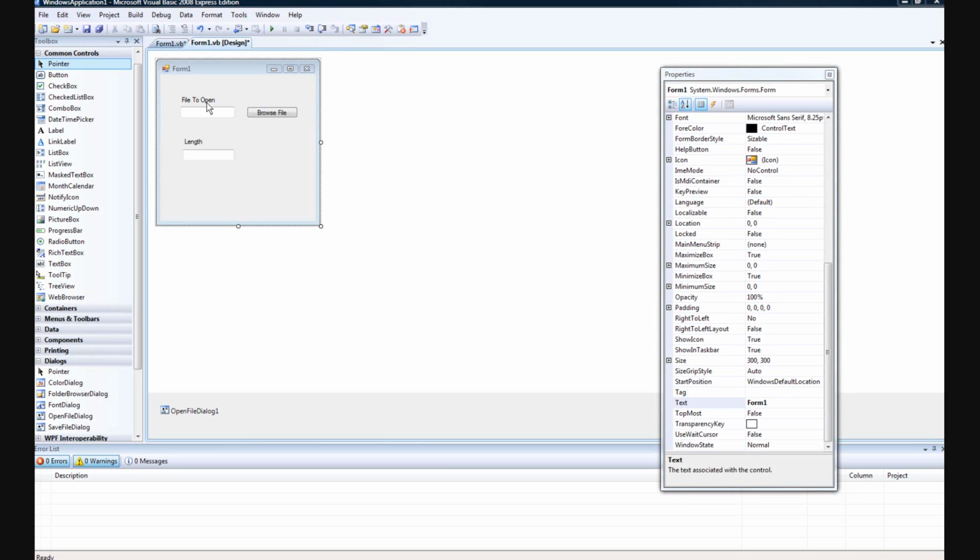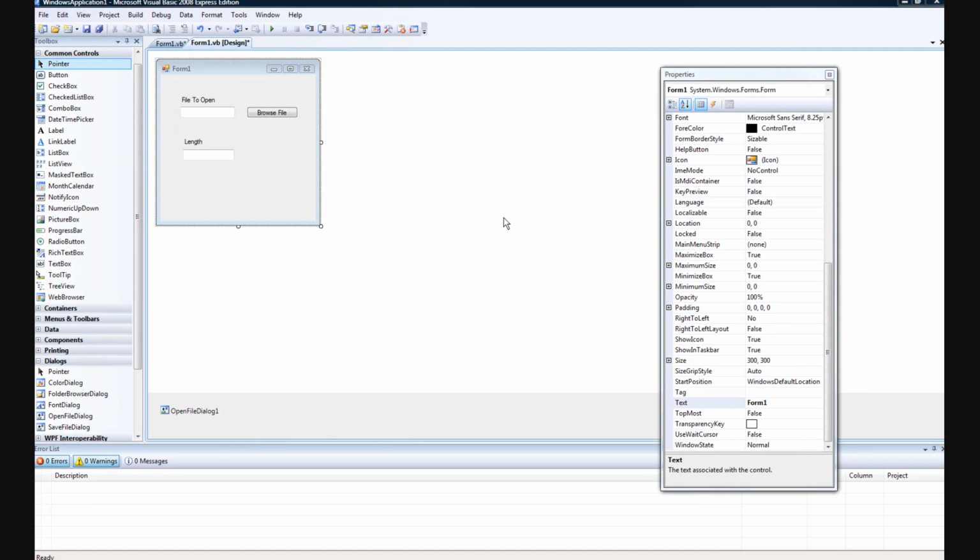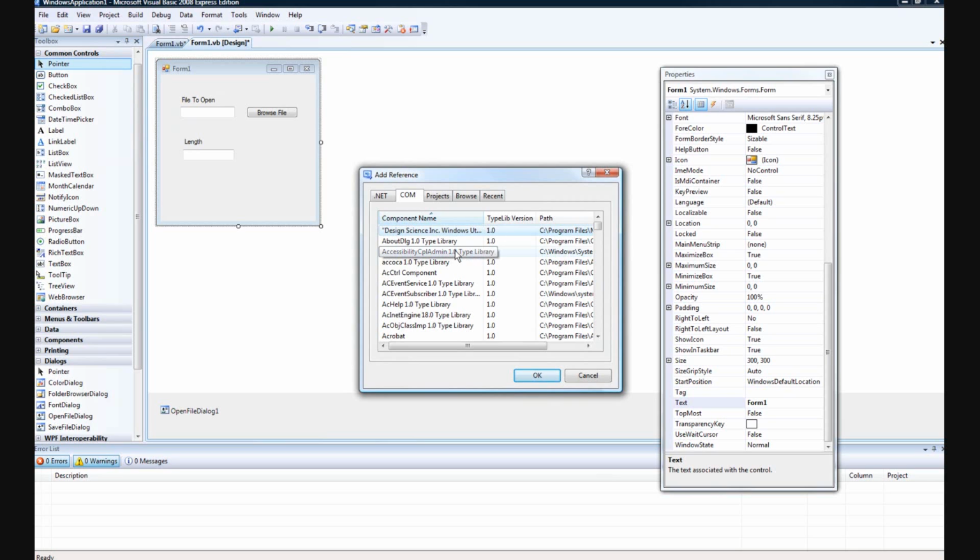And now, this is the most important part, to establish the relation from Visual Basic to GSA, we have to add references. So if we now click Project, Add Reference, we first open GSA, so here you go to COM, GSA, okay.